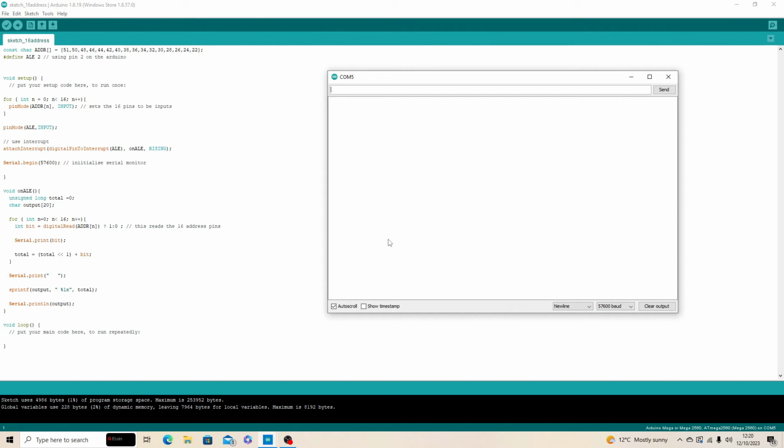Start the serial monitor with power on, stepping through, reset, and what we're looking for is incrementing through the addresses 2 at a time, then jumping to the new address and outputting 0, and then jumping back and incrementing again in a sort of cycle. And that's exactly what we're seeing there.